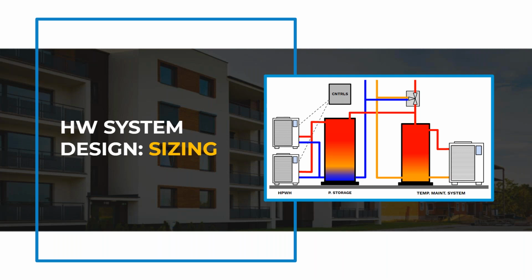And Ecotope studied that and seen that, yes, even though people use less water at 4 a.m. in the morning, there's still some people that get up and take their shower then. And so we need to have hot water available for them at that time. And so that's why those circulation pumps, I'd say, are nearly operating continuously, even when we have some kind of design approach to reduce those losses or stop that pump for periods of time.